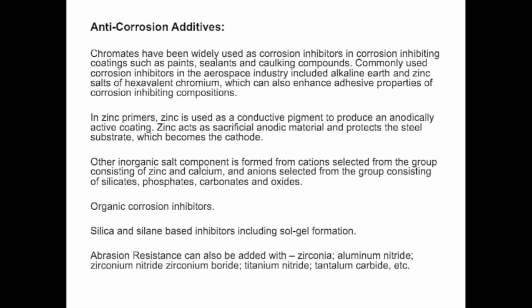Additives are sometimes used to improve the resistance of the coating. So other than providing a barrier material, things like zinc, organic and inorganic salts, and silanes are used to prevent diffusion or control the electrochemistry, such that before the carbon steel is reached, let's say a sacrificial anode or sacrificial material like zinc is consumed, or a silane agent reacts with water, or other types of salts react with water to form an oxide that then serves as an additional preventive layer.